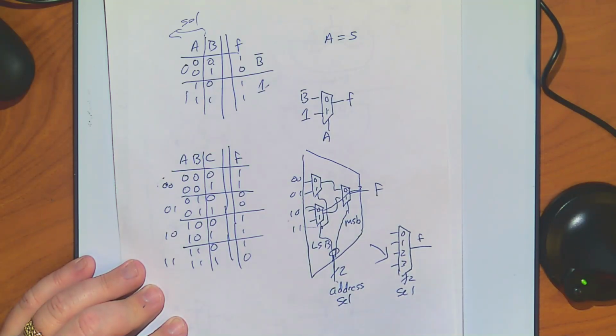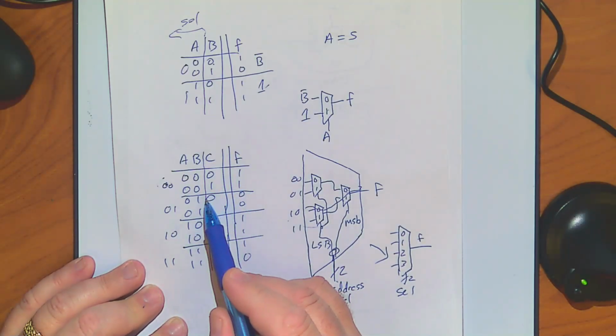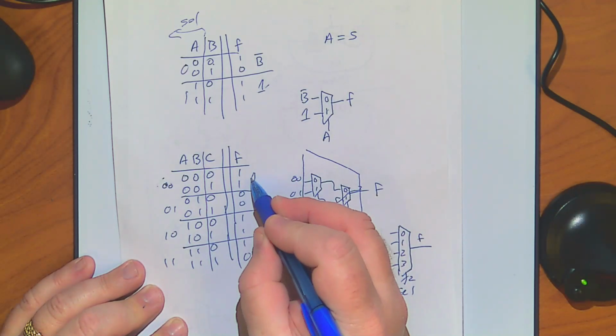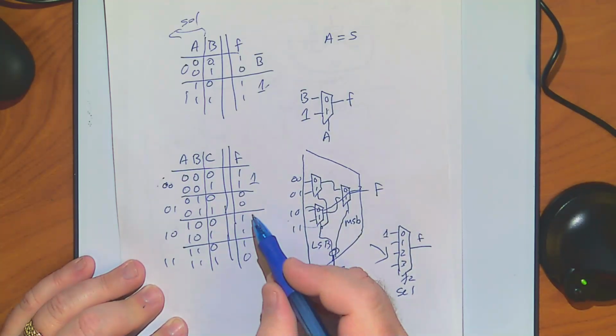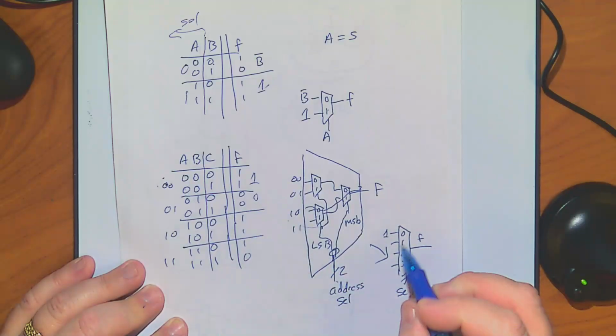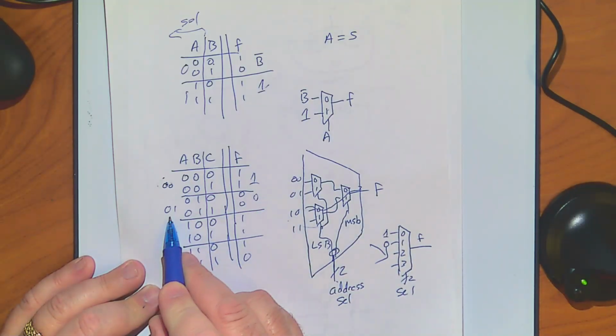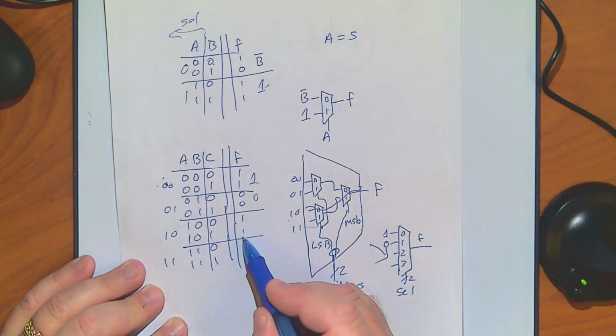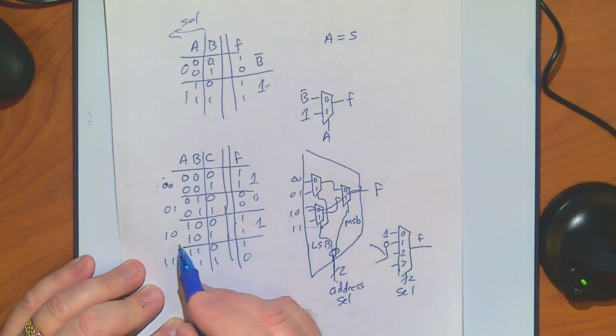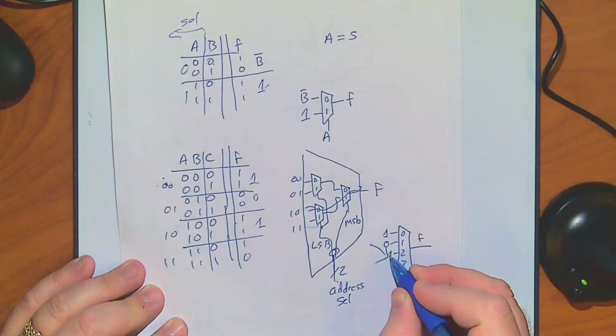So transmission gates really have a very good place in implementing a lot of our hardware code. But anyway, just to finish this one off and show you what you do here, we grouped them up. I'm just going to take a look at these and compare them to C. These are both 1s, so I'm going to put a 1 on that input. These are both 0s, so I'm going to put a 0 on the input for 0, 1. These are both 1s again, so I'm going to put a 1 on 1, 0, or 2's input.